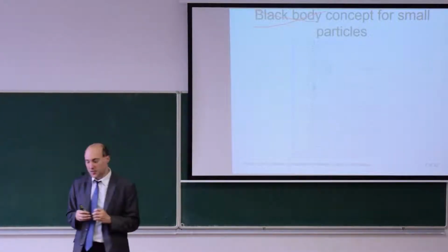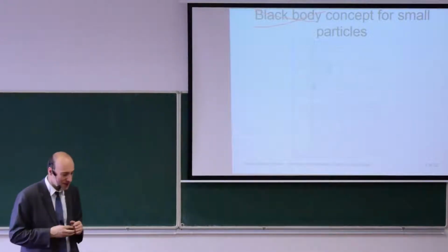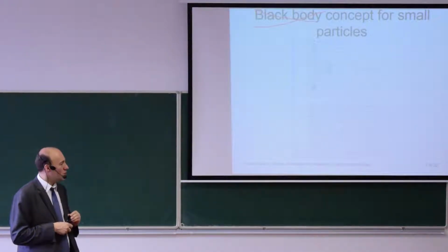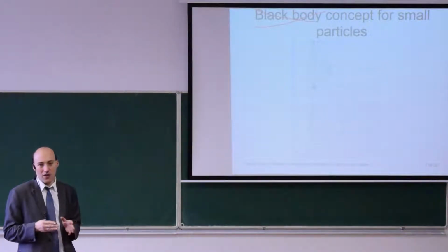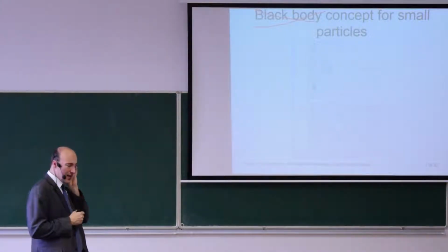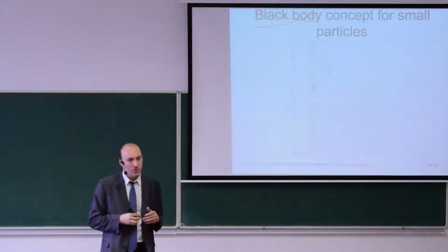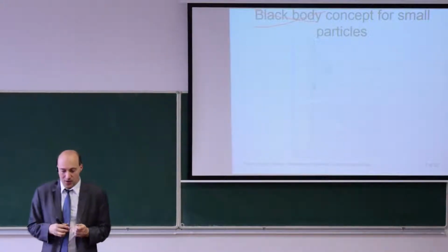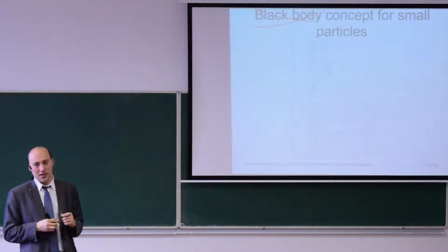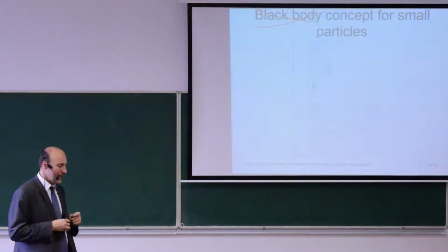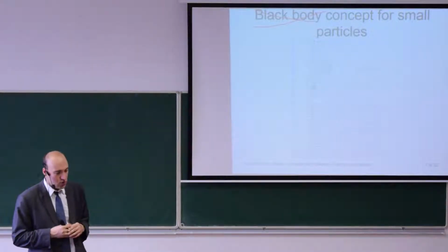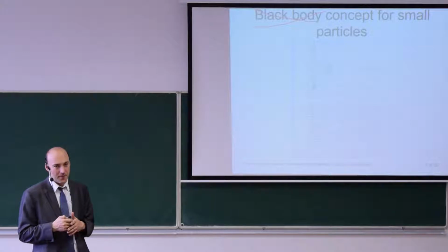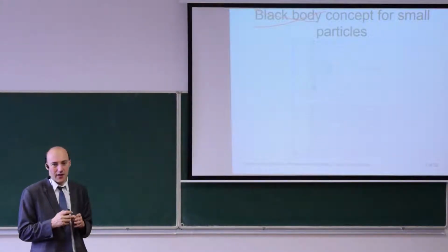The dust particles may be similar in size compared to the wavelength. Let's say we measure at 1 micrometer wavelength, so 1 micrometer size is nothing unusual for dust particles. And if you have applications where you have those particles, then it may also have a significant influence on what you measure. The reason is that the small particles, when they have similar size to the radiation, will influence the electromagnetic field around them.